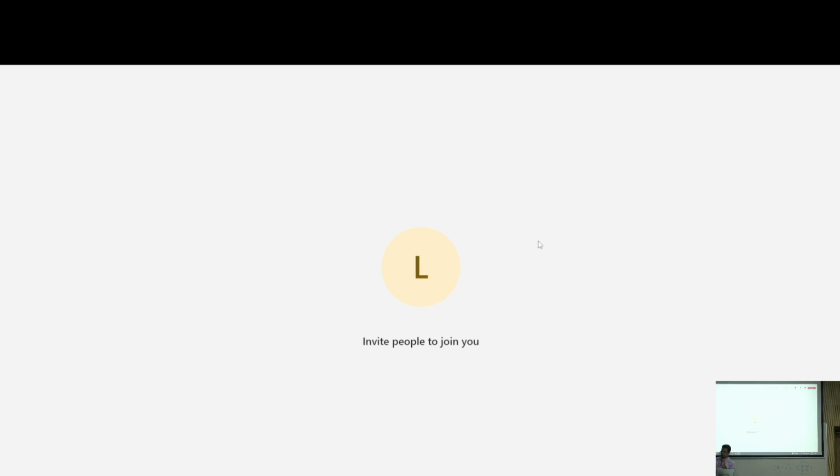Then you need to compute what is the distance you need to be from the bridge to be able to map that out. And a rule of thumb in photogrammetry is 3 times the GSD. So you compute the accuracy, then you compute the GSD, and then you can use the GSD to compute the distance to surface based on your particular camera. Okay.